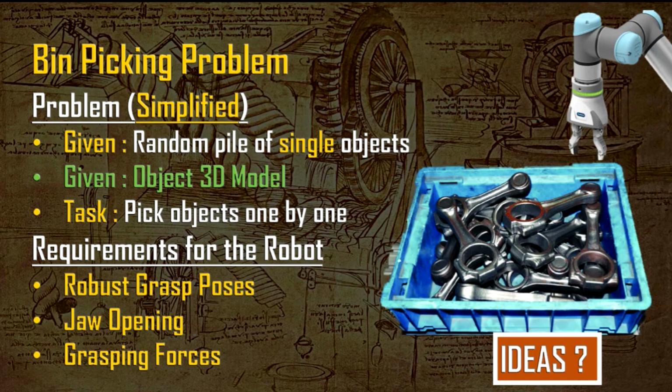And then when the robot needs to do the testing or the actual real case scenario, there will be a camera at the end effector through which we can determine the orientation of that object which is lying in the box. Since the robot is already trained to catch the object from a particular point, it will determine the orientation, and the end effector has that motor, right, through which it can rotate. So it will rotate to get the same orientation which we have trained it for, then pick the object from that same location.